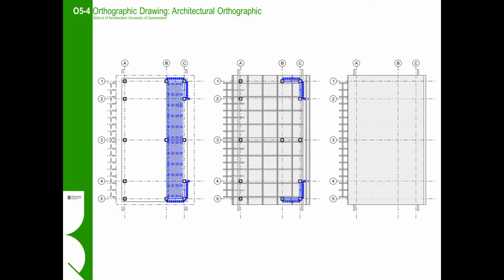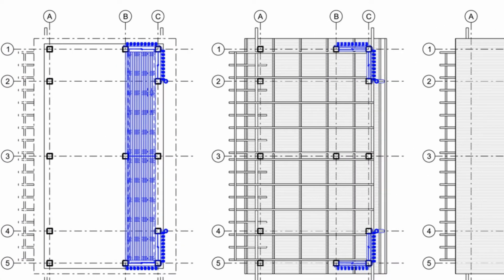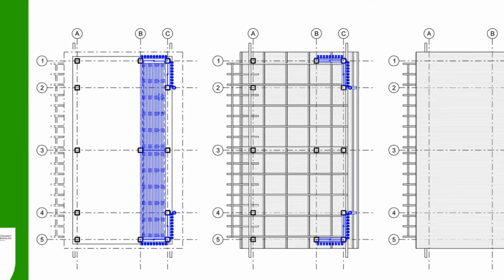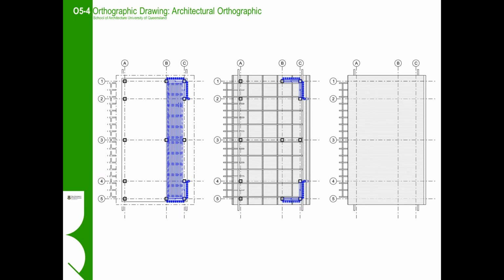In this instance, we will add in elements such as the built-in seat, the bracing elements and the timber screen, as well as small things like the location of the downpipes. It is important to concentrate and to ensure that such elements are picked up in all of the views. When we start working in 3D CAD, this is done automatically, and so the coordination is not as problematic. However, the process of constructing or building up the drawings through progressive layers is the same whether we hand draw or document the building in CAD.